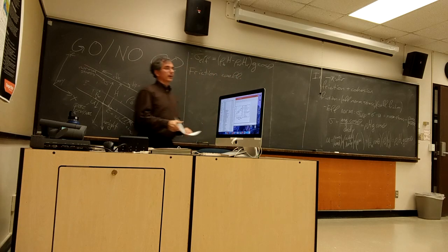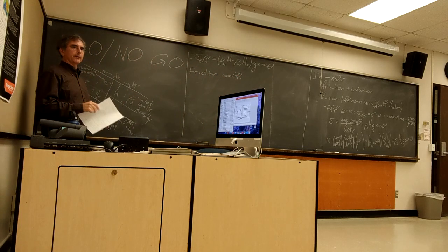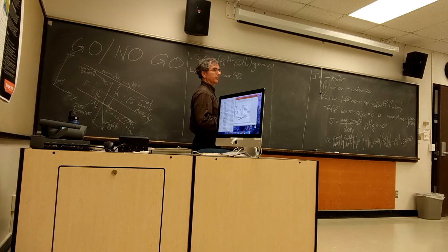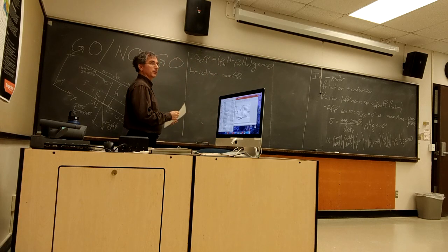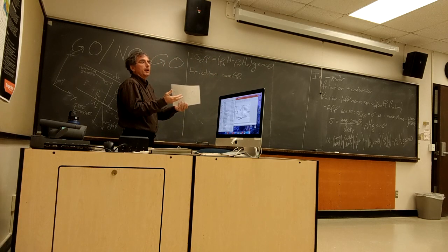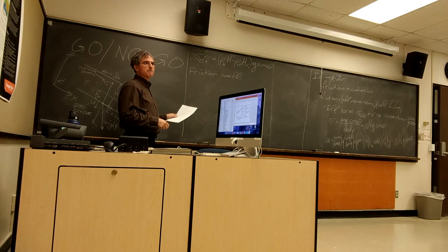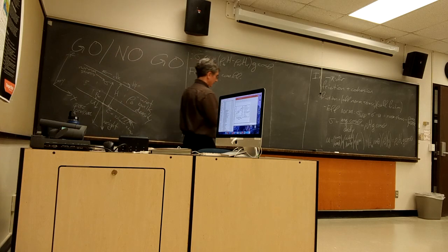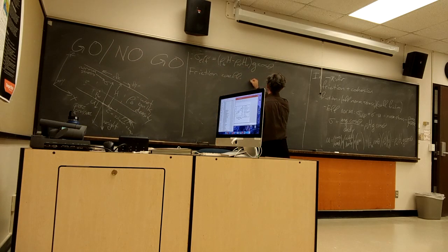I've already talked about the angle of repose, and several people have sort of nodded their heads along. Okay, yeah, I see. So how do we measure the friction coefficient? Well, we do so by measuring the angle of repose. What's the angle of repose? It's the steepest we can pile up the stuff when it's dry. So essentially, if I put up a table and I say my material is sand and I pile the sand on there as steeply as I can, then that angle we'll call phi.